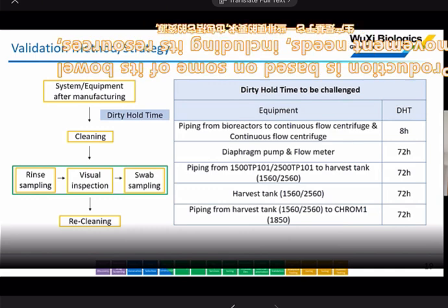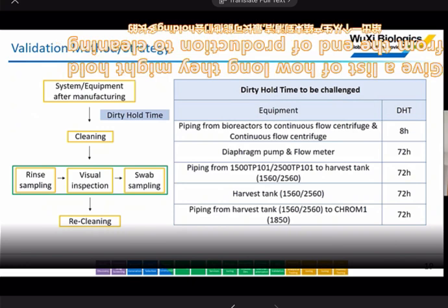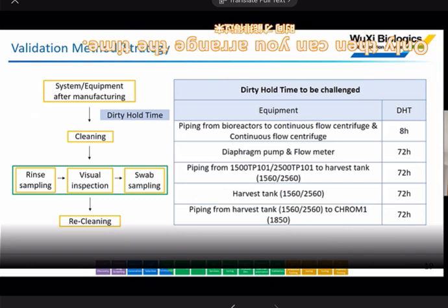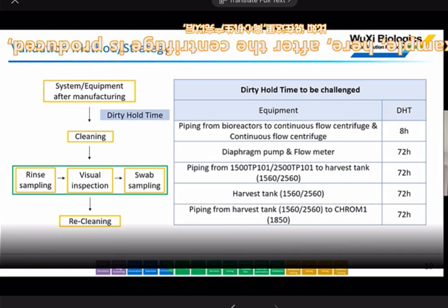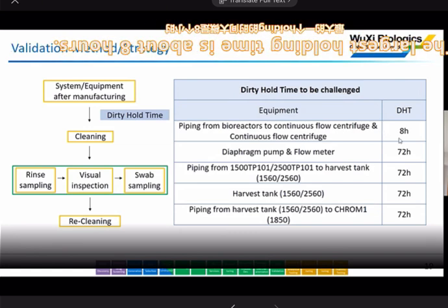If it's for similar devices, we take the biggest or worst case, do it 3 times, then just do the middle one once. So, based on these assessments, we decide which things need to be done in 3 runs, and which can be reduced, to lower the cleaning verification workload.